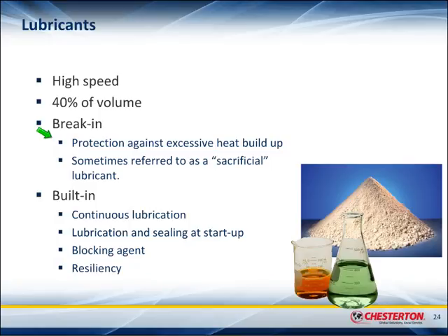And it's referred to as well sometimes as a sacrificial lubricant. And then we have built-in lubricants, and they basically provide continuous lubrication. So that's the lubricant that is contained in every single fiber in the structure of the packing. And that is the lubricant that basically gives sealing during the entire life of the packing.